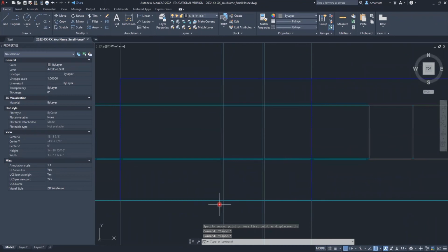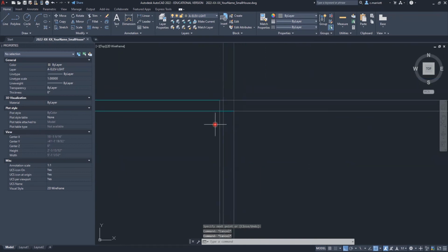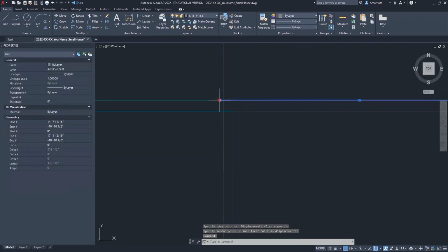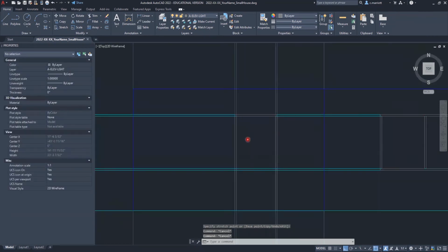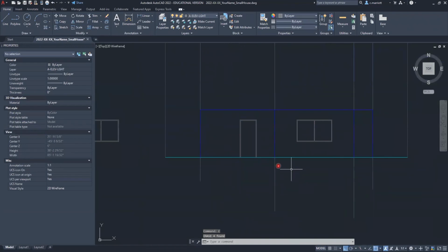Instead of using the rectangle tool, I would maybe use a line tool, and I'm just going to trace this door around. Okay, and again, it's a 7-foot high door. So I missed my line here, it did not snap to the intersection, so let's fix that. Okay, there you go. That's what a door would look like on the elevation. All right, door, window.